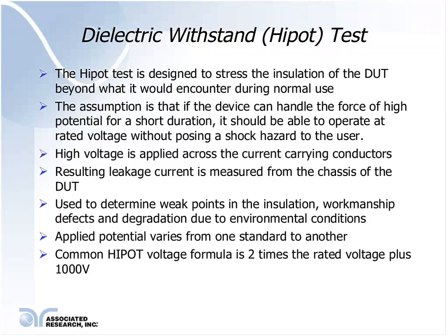As we all know, it is also known as the Hipot test, which comes from the words high potential test. This test is designed to stress the insulation of the device under test far beyond what it would encounter during normal use. The logic behind running such a test is that if the device can handle the force of a very high potential for a short duration, it should be able to operate at rated voltage without posing a shock hazard to the user.